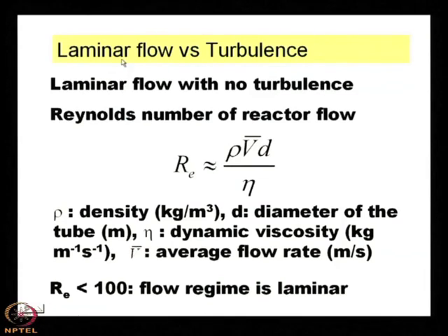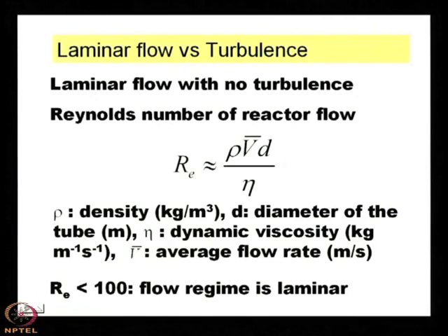Laminar flow means the flow will be in a particular direction, free from any distortion. It will start from one point, take the same path and reach the same point. Which will take the same path? The gas molecules. In our case, we are talking about the gas molecules, in which all the chemicals are embedded. So, we are concerned about the flow of the gas inside the reactor. Now, for laminar flow, we have to take the help of the Reynolds number.